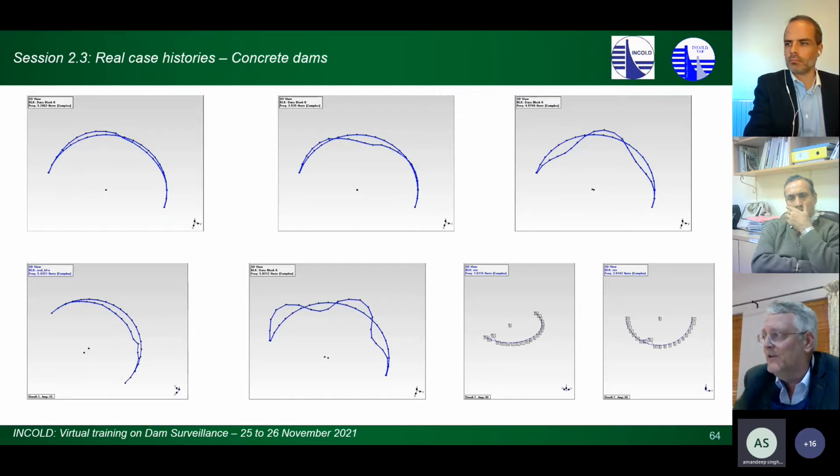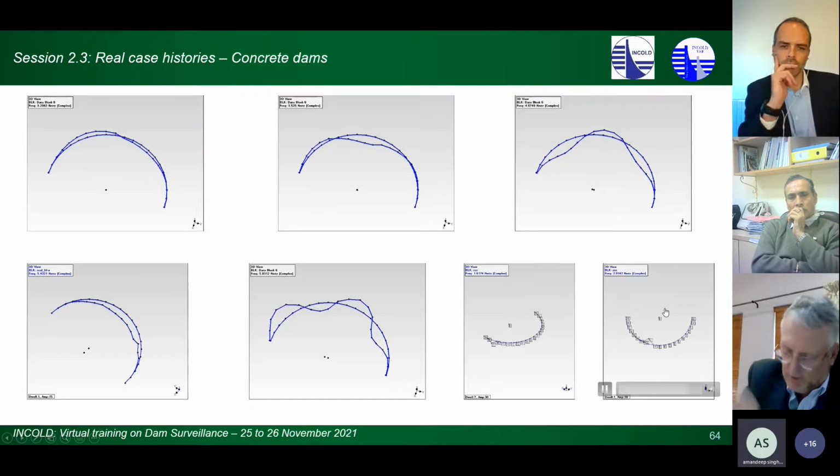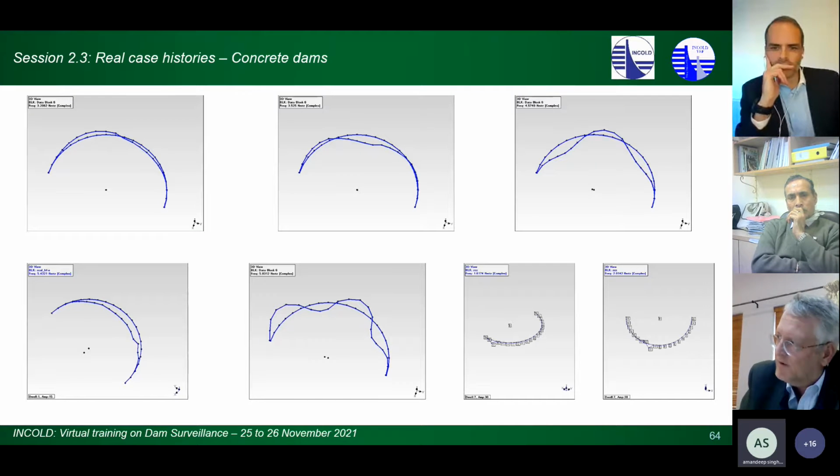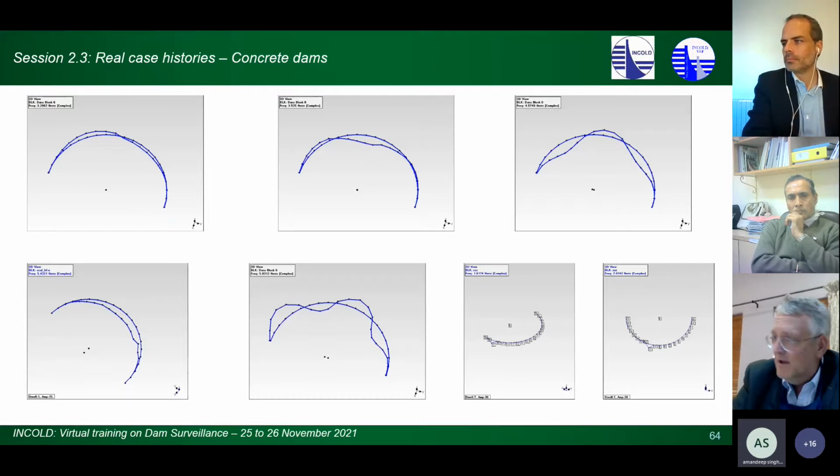So we thought there was something wrong. But the results of the AVM showed us that yes, those blocks are actually moving up and down as well. They lose restraint if the water level drops. Because of the swelling, these blocks become really cantilevers, and the top parts are actually moving.